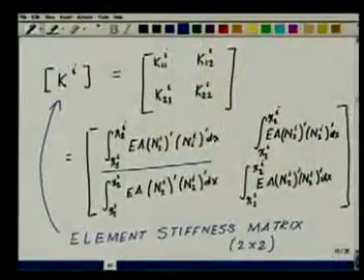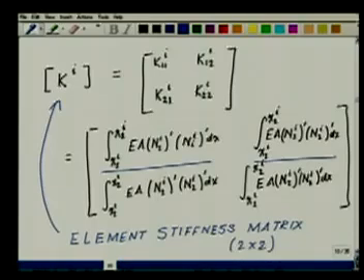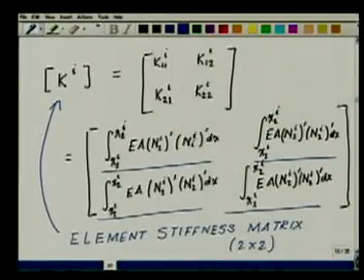All other phi_i's are 0. If there were more phi_i's, which we will see later on, which are non-zero in the element, the matrix size increases by that much. So this is the element stiffness matrix, and you see that we have now computed the entries of it. What we had done in the previous page, we have simply rewritten in terms of the element notations that we have introduced. So they are given in terms of the element level entities.